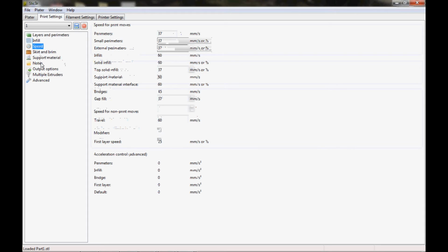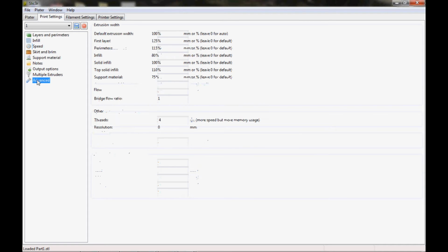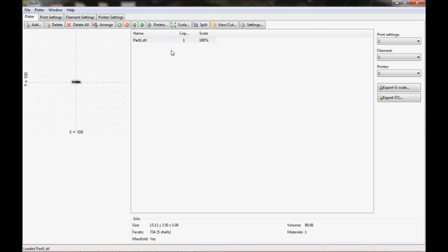Speeds of 3D printing, how much of an override for extrusion width, which is basically how much material it pumps out of the extruder, are all controllable. And then once you're happy with those, you create what's called a G-code file, which allows the machine to read a standard coordinate system, instructions on where to go and how to go.